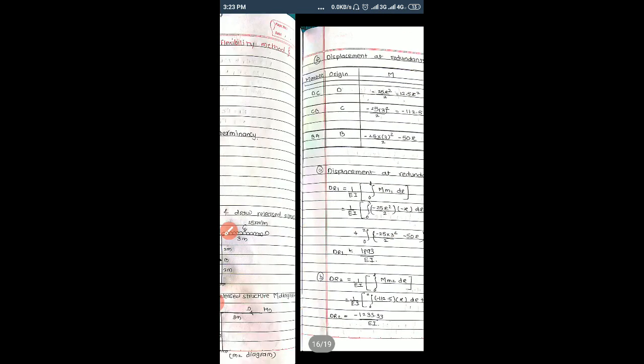Now the next and last part is to draw the shear force and the bending moment diagram. So we will complete the numerical likewise. Okay, so as you see, there is no change in the analysis of the portal frame. It is the same as in the case of the analysis of a beam, but in the first step over here, in the degree of static indeterminacy, for the beam case we have neglected axial force. Okay, but we cannot neglect it in portal frames or columns. Okay, so we have to consider that axial force also.